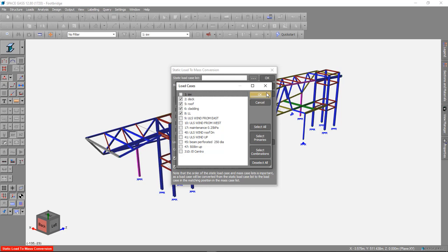What I'm about to say next about live load has been edited into this recorded copy of the presentation in response to comments made by some people who attended the presentation. They pointed out that live load shouldn't be used as a mass in the dynamic frequency analysis. This is correct, and we probably shouldn't have included it as a mass. If live load is present when the seismic event occurs, then it certainly affects the dynamic response of the structure. This could result in lower stresses in the structure than if it wasn't present, and so you might find that including it as a mass may be unconservative. Ultimately, it's up to you to decide.